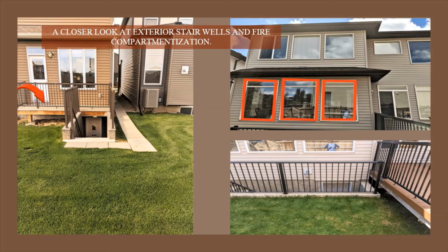In the example on the left slide, there is a deck going across the door, so it is now protected for the person to come upstairs. But on the right side, we couldn't put any form of structure over the stair. So we had to speak with a code specialist who can extrapolate the code enough for us so that we can place a sprinkler head within the windows. The sprinkler head will control the fire and allow enough time for the tenant to escape the suite.